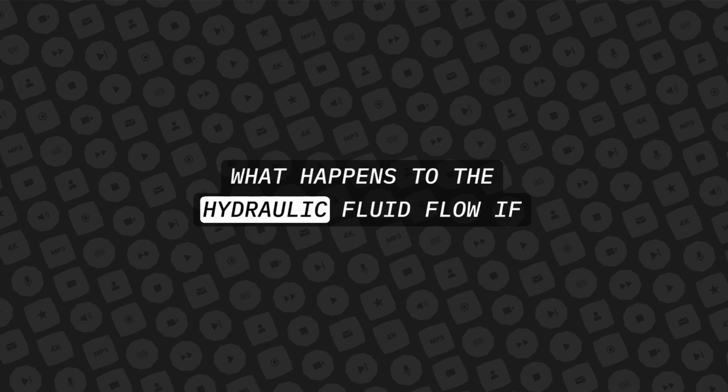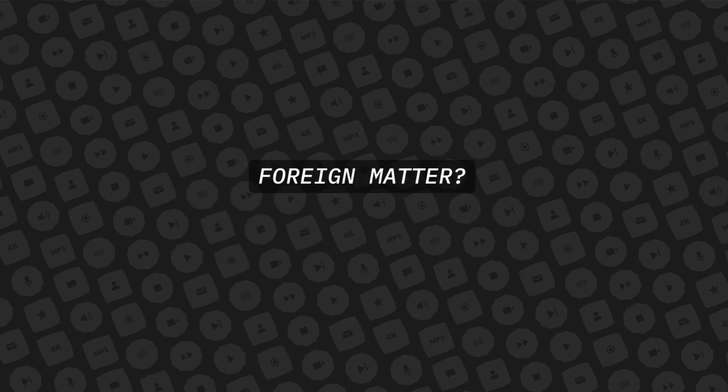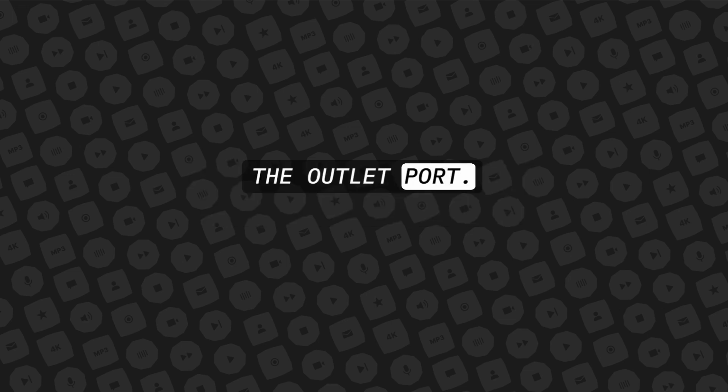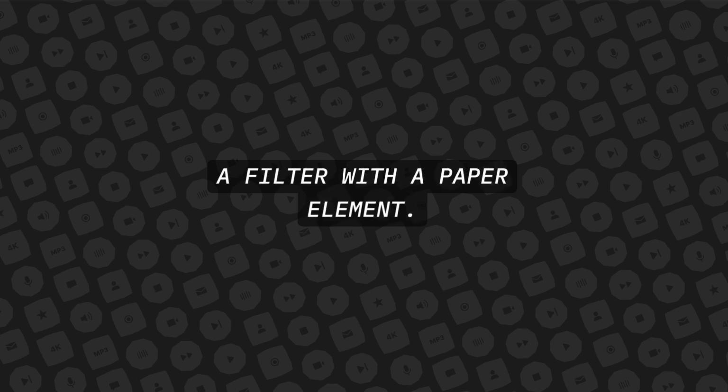What happens to the hydraulic fluid flow if the filter element becomes clogged with foreign matter? There is a bypass valve, which routes the hydraulic fluid directly from the inlet port to the outlet port. What is a micronic filter? A filter with a paper element.